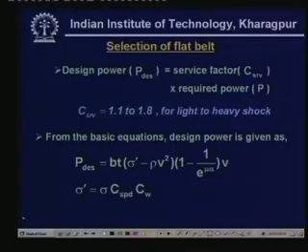You just see it is given in blue color, that is, the service factor is normally 1.1 to 1.8 for light to heavy shock loads. Well, this is a guideline. Okay. So, if you want to be very conservative, you can just straight away take 1.8, but it will not be very economic for you in that particular case, because conservative designs are always too costly.